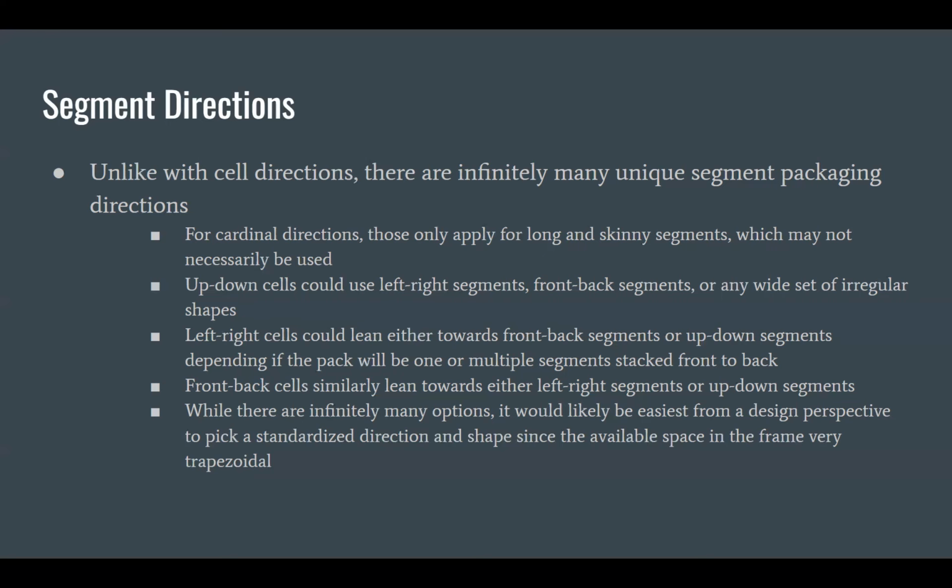Do you wire the segments parallel? All of them are in series, but we can do whatever. There are no rules; you could do them in series or parallel. But because we have a 140 series, 4 parallel cell configuration, they don't explicitly ban it, but they very strongly recommend that you do not run segments that have cells in parallel but in separate segments.